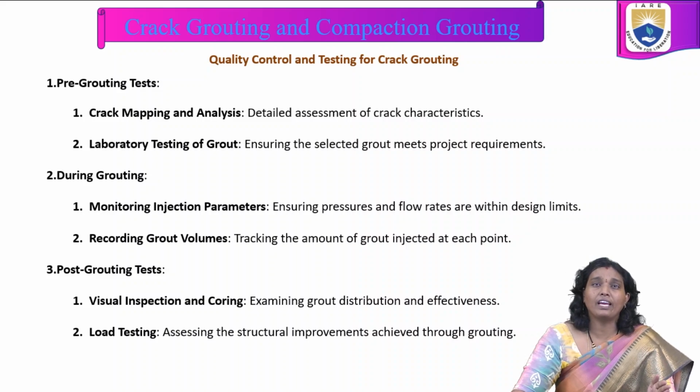So coming to the pre-grouting test, crack mapping and analysis, detailed assessment of crack characteristics, and coming to the laboratory test, we are conducting it ensuring the selected grout meets project requirements or not as a part of quality control. Now, at the time of the grouting, we are ensuring pressure and flow rates are within the design limits.